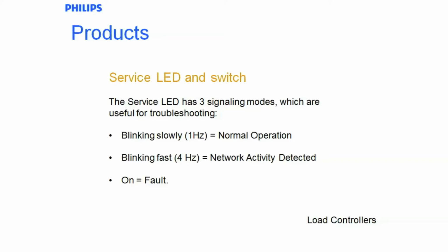The auxiliary input on the load controllers is not used in a lot of applications, but it can be used as a dry contact, low-level interface with a max 2 meter run-through. Low-level means it's a simplistic interface with only 2 states, on, off, or open and closed. It can be used for an emergency light trigger or local security interface if you wanted to. In the case of security, that dry contact is between AUX and ground and is an active load. When you put a short circuit between the ground and AUX terminal, that's the active state of that input.